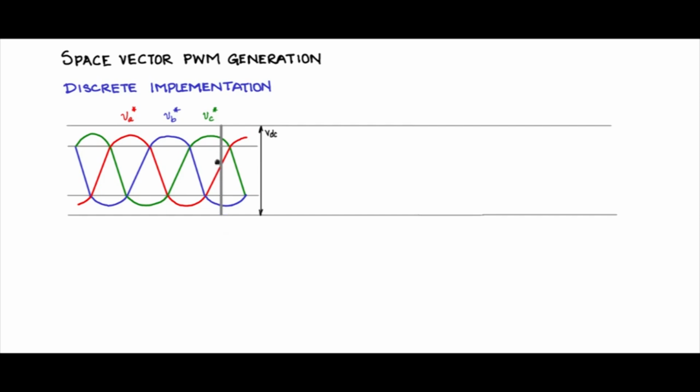Now, the carrier signal is there in this one. So there is a triangle. The three-phase AC signals are at 50 Hz and lower frequency if it is motor drive, but if it is for grid connected inverters, this is fixed at 50 Hz. It will be more or less at 50 Hz. But you could use the same space vector PWM generation that we are discussing even for motor drives, where it could have a varying frequency. But for now, consider that this is the grid frequency.